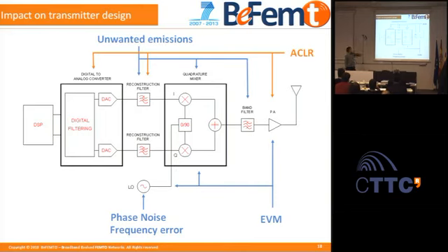That means that the frequency of the carrier is the same as the local oscillator. This is the reason why it's called direct conversion. After the signal is produced in the mixer, it is filtered, because you have to take great care to avoid unwanted emissions in order not to interfere with other systems, and finally it is amplified to the proper level in the power amplifier.